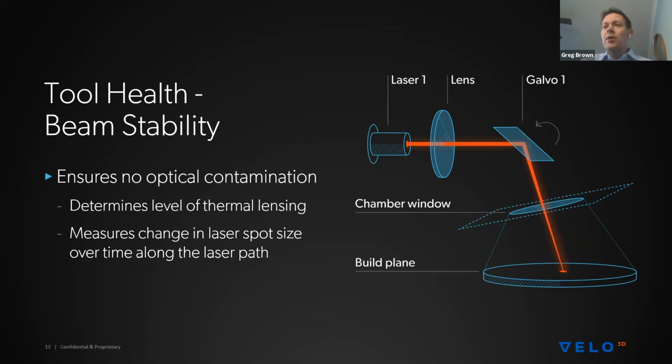On the other side of things, if you're looking to do contours or skin processes, oftentimes you're looking to use a very focused beam where you're trying to individually trace out small melt pools that give you the best surface finish as possible.